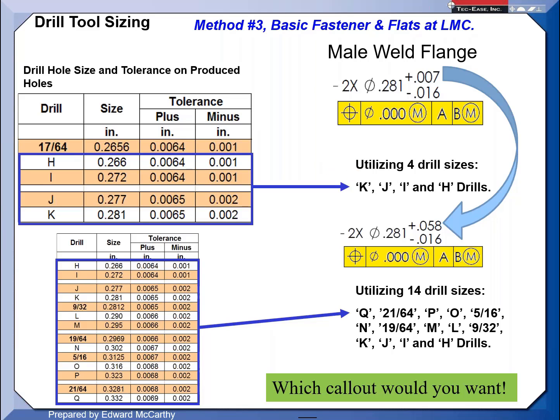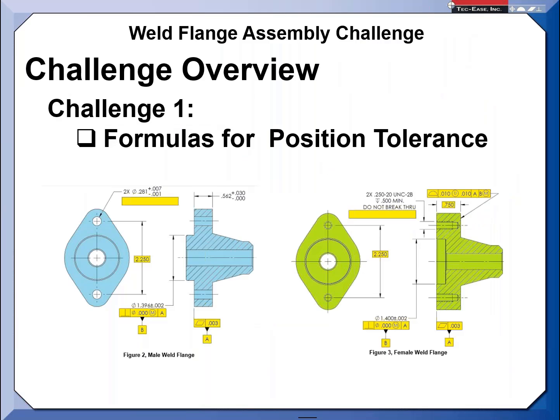All these exercises were about, first challenge, are you aware there are standardized formulas in the ASME Y14.5 that, if you utilize them, let you look at this whole joint collectively, not individually? You'll have individual contributors like the tapped hole and the clearance hole, and then when I thread the bolt in, based on whatever this threaded hole's doing, collectively, what's the bolt going to act like?